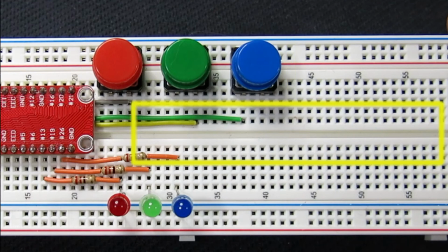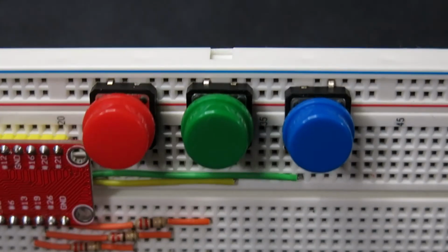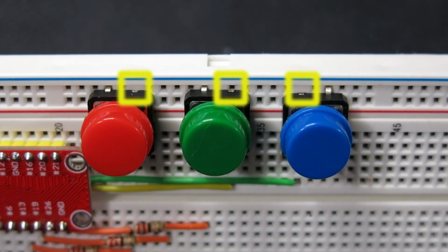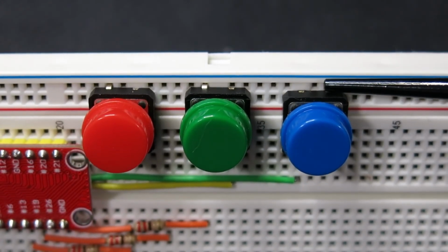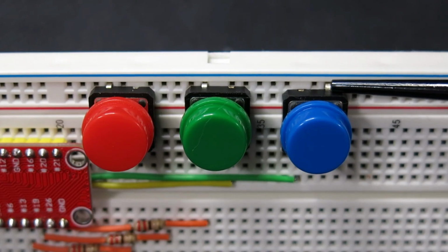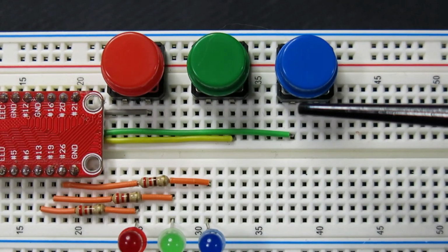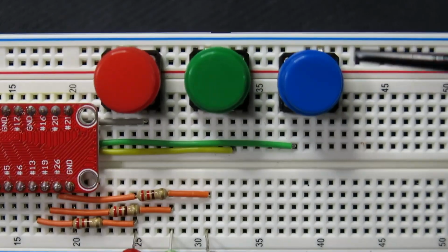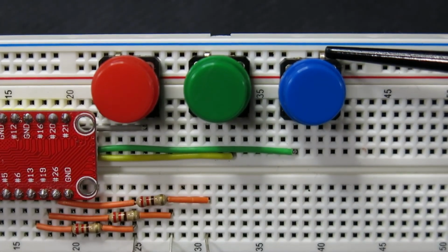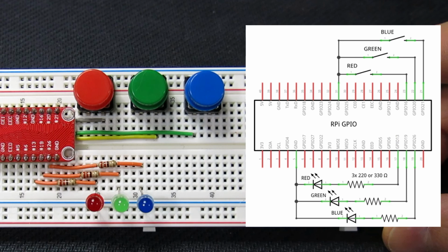I don't want to bring it over from the other side, as I like to keep the breadboard wires to a minimum. The minimalistic goal is also why my buttons are placed in what some may see as an unusual location. Most people place their buttons in the middle of the breadboard. I choose to remove one pin from my buttons, which allows me to plug them in directly into the power rail. The incoming connection is on the diagonal from the grounded pin. That's it for part 1. We are ready to start the code.